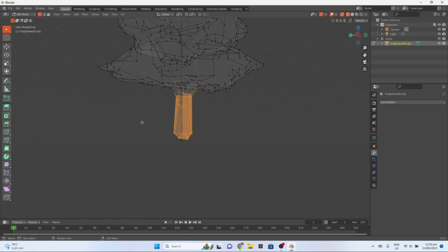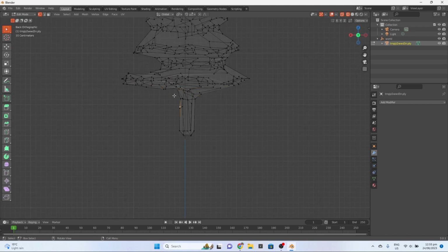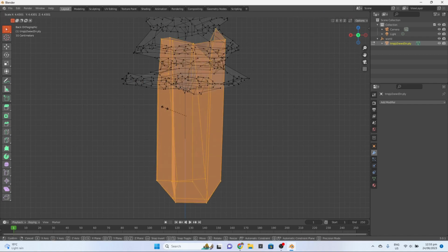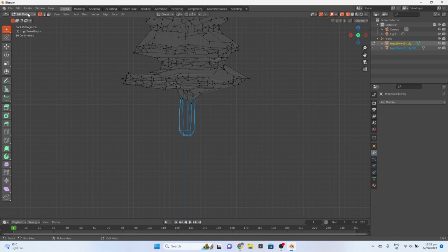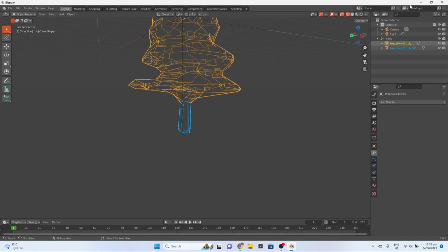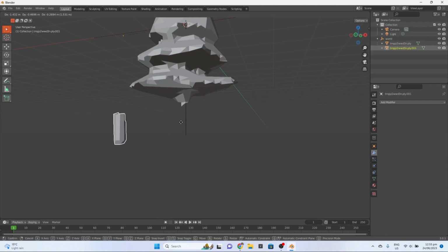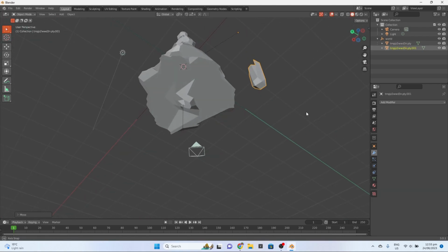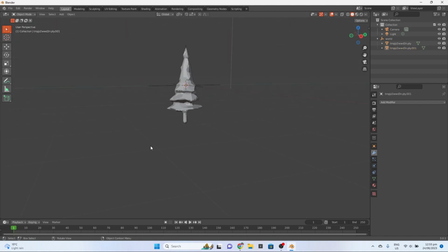I don't know how that face got caught there, but just set your view to one of the side views and bulk select it, right click it and separate it by selection, go into object mode, set it to solid again, and then just click G here, and you can see that they're separate. So undo that, and you'll be able to texture it as a separate part in Roblox.